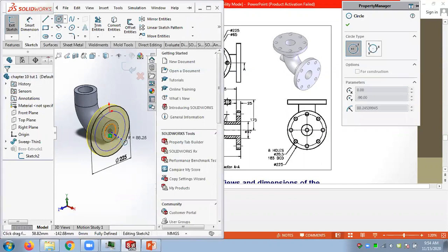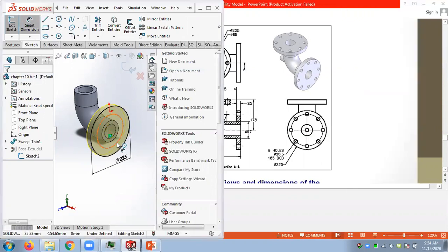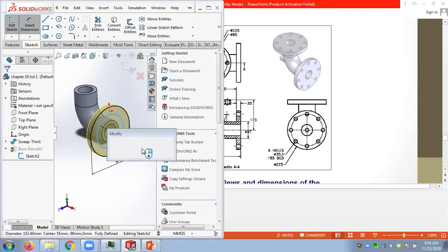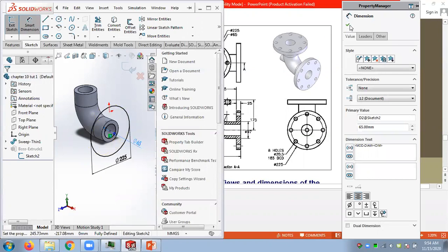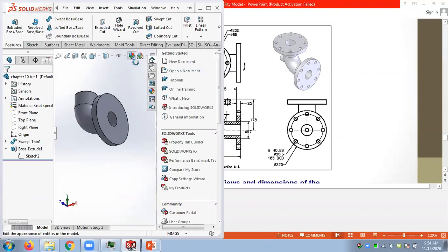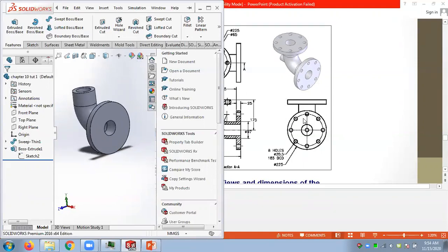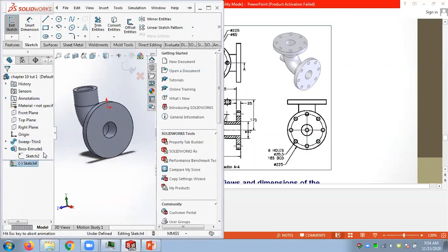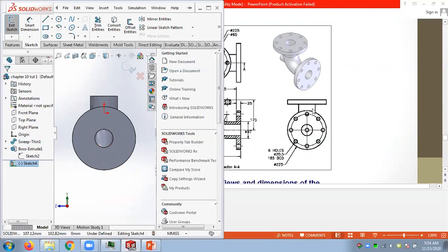This is going to be 65. So from the same extrusion, I can get it without cutting. Then we have these small holes. The bolt circle diameter is given as 185, and the circle diameter is 20.5. So we get that. You want to make a vertical sketch to the screen. Then we can easily draw this line and these horizontal and vertical circles.